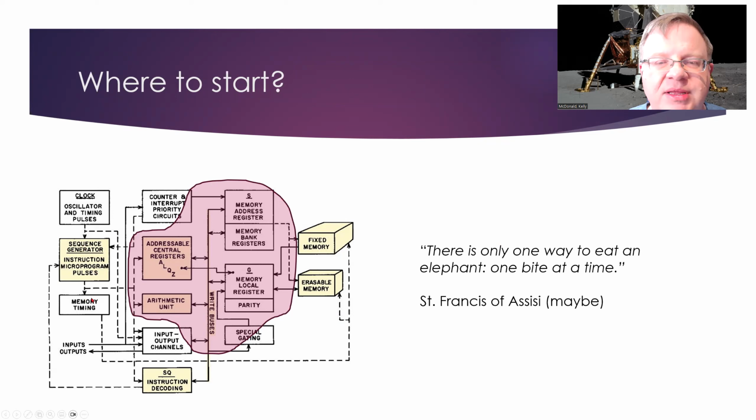We've got memory timing. This is something where we're taking advantage of some more modern components. We're going to be using modern erasable, electronically programmable memory for the ROM portion, and we'll be using static RAM for the RAM portion.